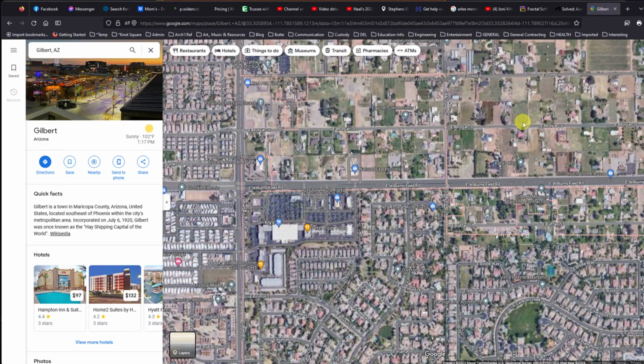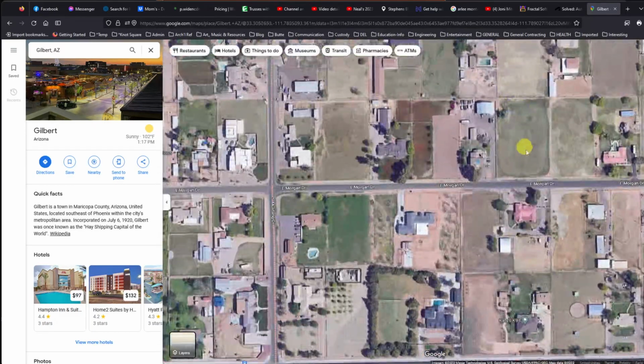And so we put up a new house here, and the water's flowing naturally this way, let's say, and this new house creates a big flood around it. There happens to be, let's say, this dark spot here. This dark spot's a swale. And all of a sudden, boom, because we put a house here, we gathered the water, and it goes shooting in here, and it floods this guy out. Now we've got a lawsuit on our hands. So in Gilbert, they require a civil engineer.